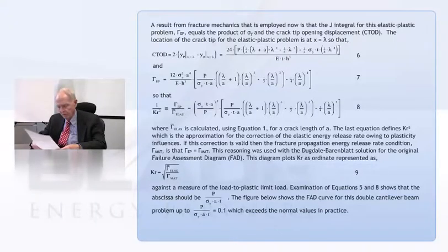So what is being done here is we're using those equations to calculate, after we've got lambda, the crack tip opening displacement. That would be the displacement where the crack ends, but not into the region that's lambda long. When we do that, with this crack tip opening displacement defined the way it always is, we get equation 6, and then we say that this energy release rate for that material, if the crack advanced and these loads were present, then you take sigma y times the crack tip opening displacement, and you have the energy release rate, which is given on the next slide.